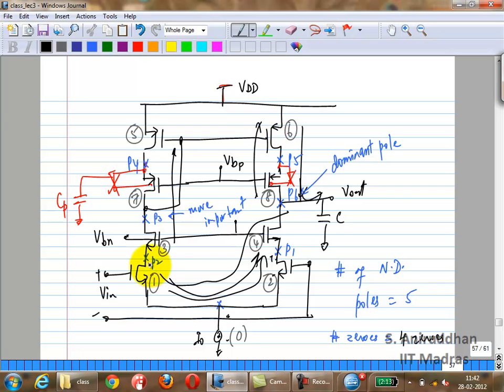However, you have to be careful when you bias these guys at minimum voltage, right? Because the closer you bias it to minimum, the more distorted the output signal will be. You already know that, right? So in a general case, you wouldn't want to bias this such that M1 and M2 are close to triode, okay?